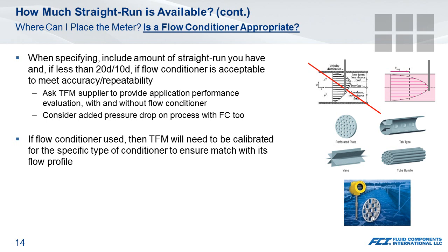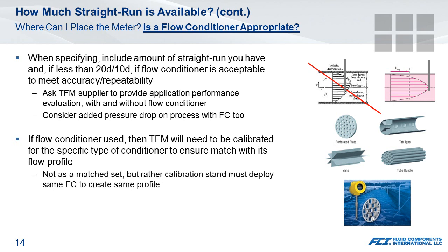If you decide after the fact that a flow conditioner is appropriate, then the meter is going to come back to the factory for a recalibration that matches the flow conditioner you're going to use.